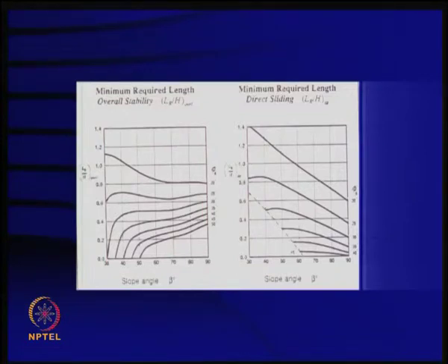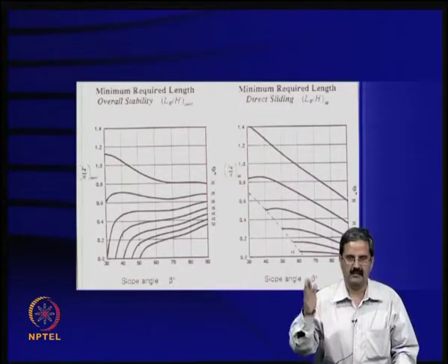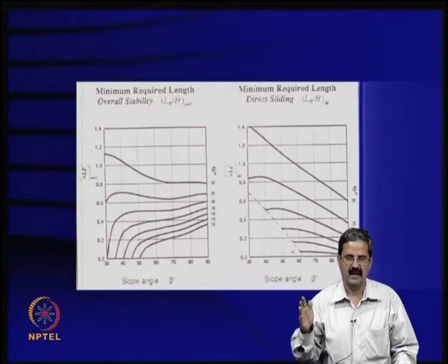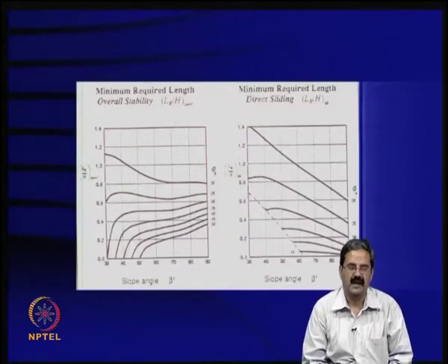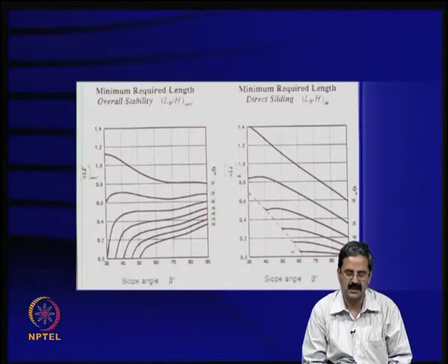One can use a log spiral failure mechanism, one can use a wedge mechanism, or one can make a two-part wedge, because it is much closer to what people have observed in the field. Why these failure mechanisms are assumed is that some of them are noted when you see that there is a failure.